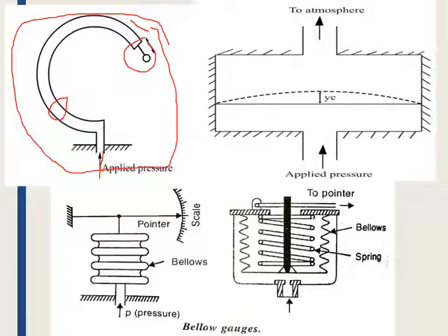Because of which a displacement is created by this Bourdon tube, and the link connected to this Bourdon tube is pulled, and this link is in turn connected to the dial indicator. So the dial indicator indicates the reading of pressure on a scale, where this is being amplified by an amplification system in between from the link to the dial indicator.